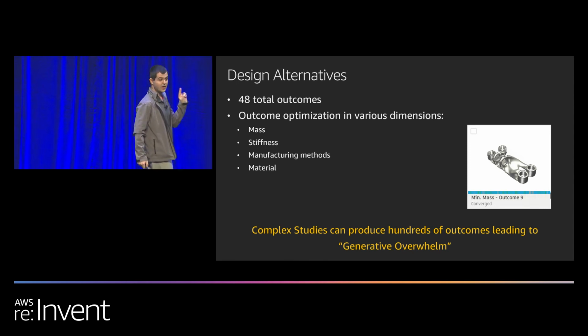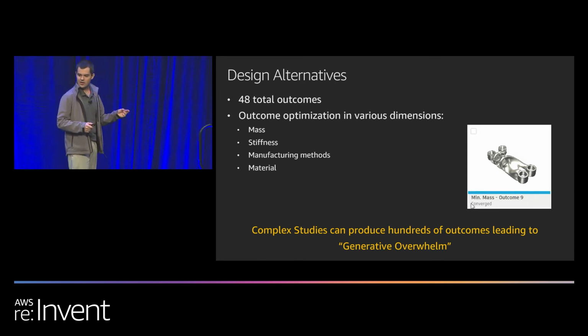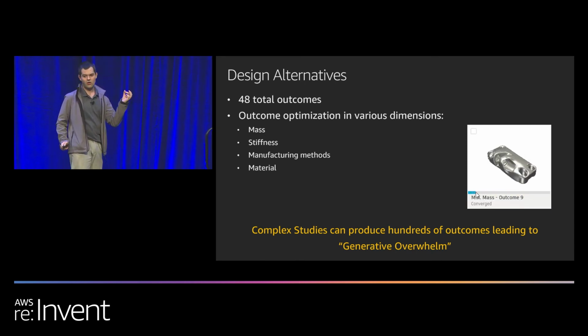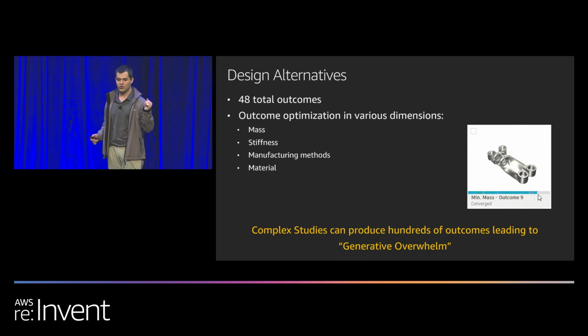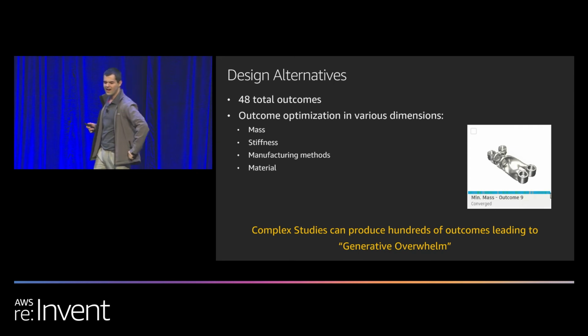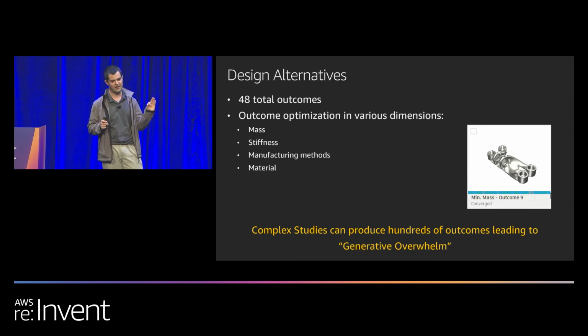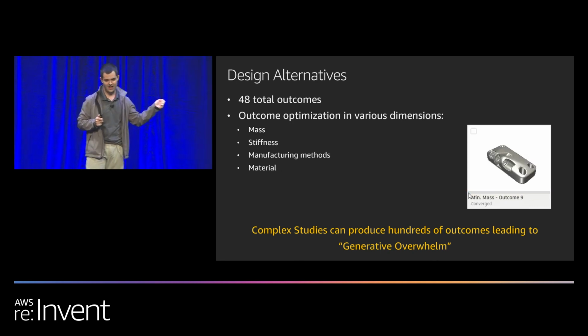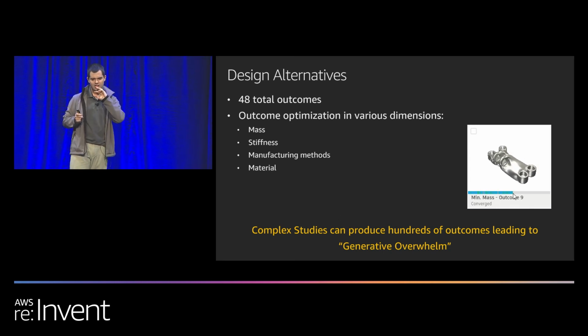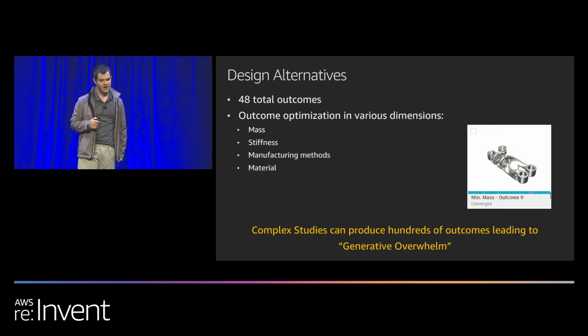If you specify a minimum safety factor of 5 and an optimization goal to minimize mass, generative design will continue to optimize until it reaches the lightest possible part with a safety factor of 5 using your chosen material and manufacturing method. So this is verified automatically with multiple simulations at every step. However, you might notice that one of the intermediate iterations is only 15% heavier than the final outcome, but offers a safety factor of 10 instead of a safety factor of 5.